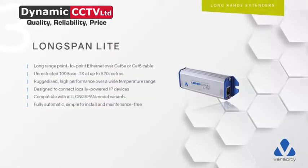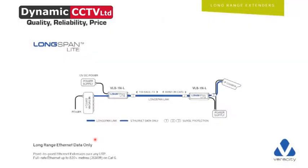So we're back to a light version again. There's a bit of a pattern forming here: we've got PoE devices and non-PoE devices. This is a non-PoE device, and again, the same distances can be achieved on this. Nathan, I want to point out that the surge is on the diagrams where we suggest you put your surge protection. The light versions are powered by 12 volts. That's important to remember in case you look at our 57 volt range. These are powered by 12 volts.